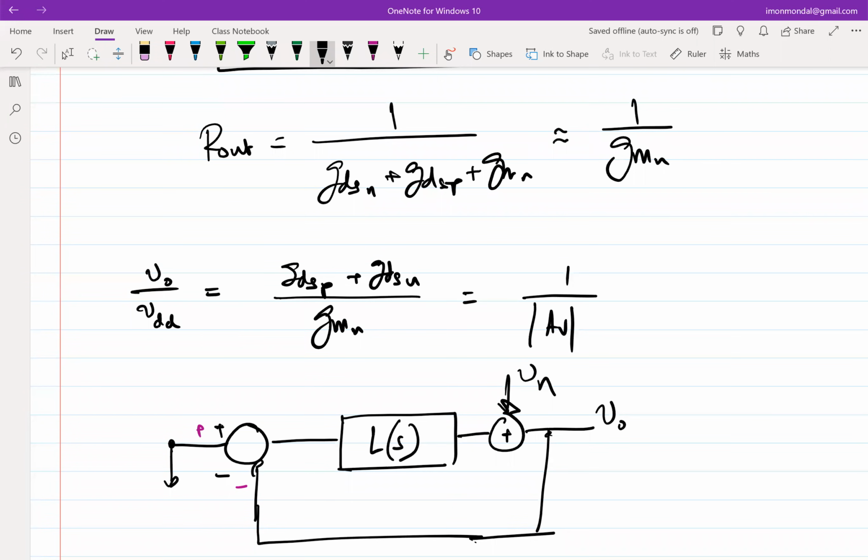You have CMRR, you can do it for CMRR, you have PSRR and everything. So those things are always normalized with respect to the open loop gain, not because it's mathematically convenient, but because the moment you put it in negative feedback, whatever bad excursions that are supposed to happen go down by a factor of the loop gain. So it makes sense to define these parameters with respect to loop gain. And it also gives you a design handle.